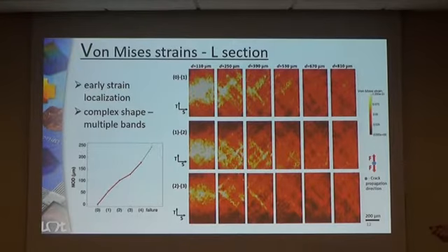This strain pattern is rather complex, in the sense that very close to the notch root in the immediate vicinity, we have this one huge horizontal band, and very soon it develops to several strained slanted bands. When going farther away from the notch root, we arrive at the slanted zone, and here mainly one X-shaped slanted band remains. Spacing between the bands is roughly 200 microns, and the bands themselves are between 15 and 100 microns.